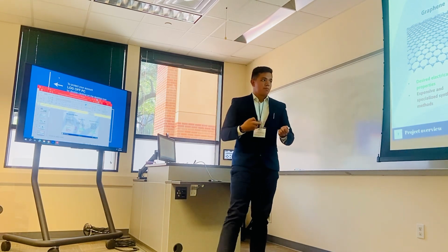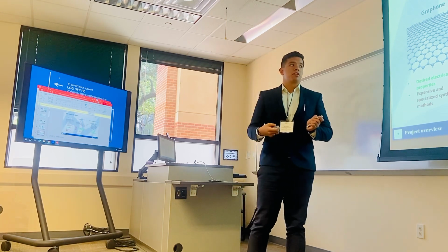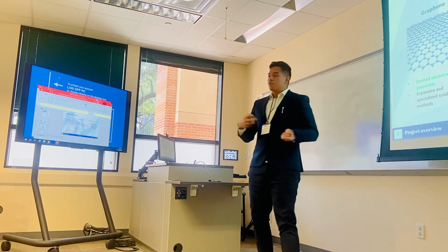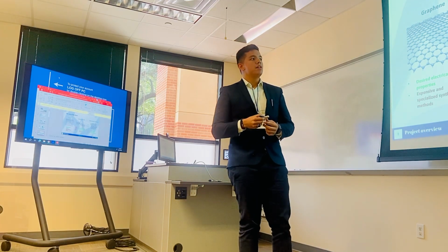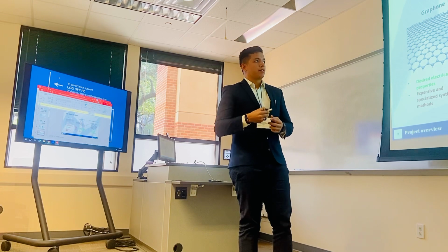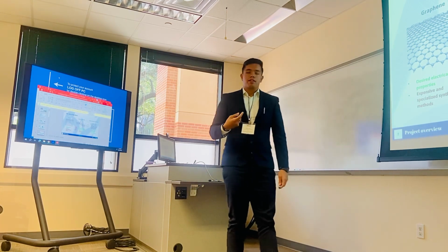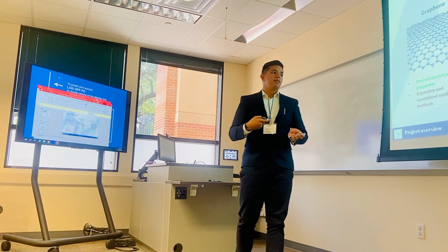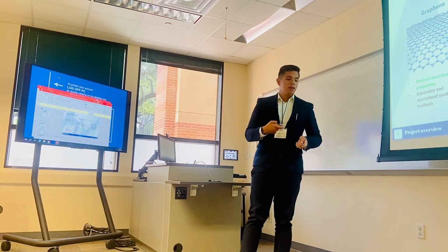And so with some reduction processes, we can achieve the version that we use, which is reduced graphene oxide. You still have some presence of functional groups in the graphene sheets, but they are considerably lower than in graphene oxide, while maintaining the desired electrical properties, and the techniques of reduction are actually quite simple.